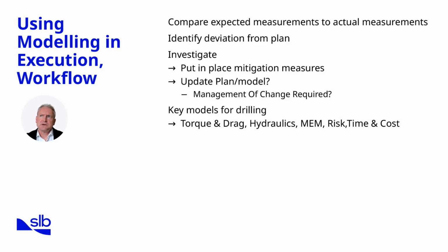Is the deviation due to unexpected geology, incorrect input data, or changing downhole conditions? Once the cause is understood, mitigation measures are put in place. This could involve adjusting mud weights, modifying drilling parameters, or deploying contingency equipment. At the same time, the forecast model is updated to reflect the new conditions.